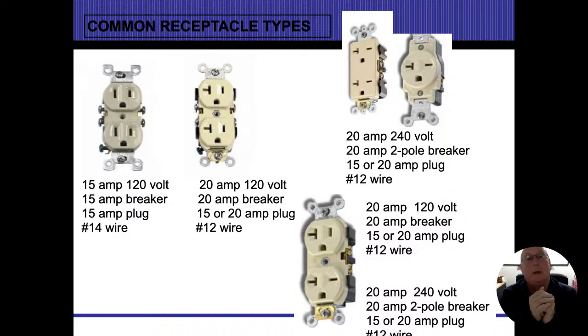I take the next one, and you can see how it's shaped like a T. So if I have the energized conductor straight up and down, and then the neutral slot horizontal, that's for a 20 amp outlet. When I get the T, as we're showing here, that's telling me that it's either 15 or 20. It'll work on either one. I could wire it up to a 14 gauge or to a 12 gauge. And I take that back. I should have only a 12 gauge wire going to those. And you will find that back on a lot of 14 gauges.